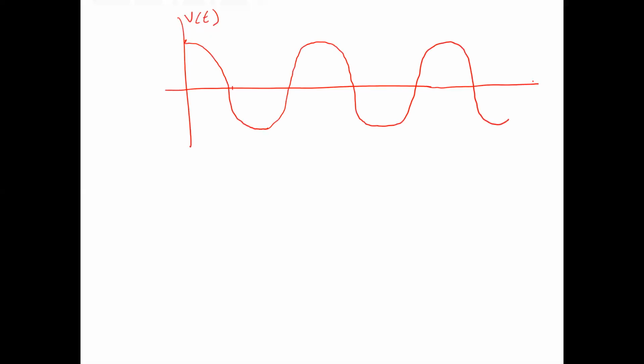Okay, that's more or less a sine wave, right? Again, in this case, suppose Vm here, which is the magnitude of that sine wave, is 10. A little bit easier to think about 10. The VRMS is going to be Vm over root 2. It's going to be 0.707 times Vm.